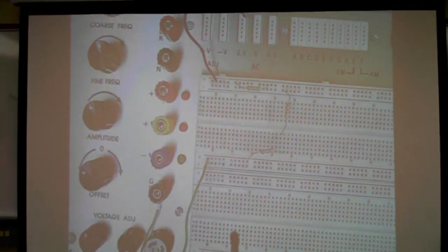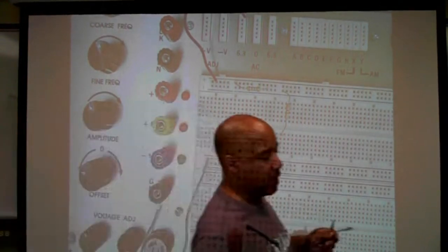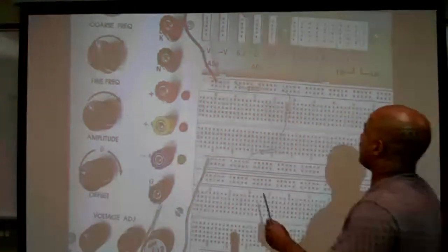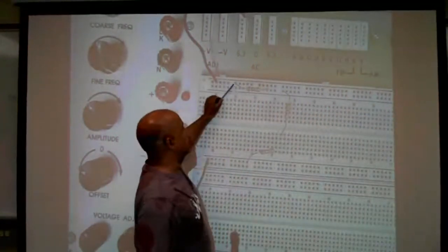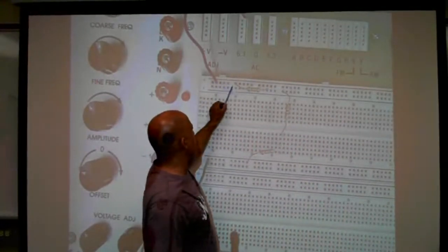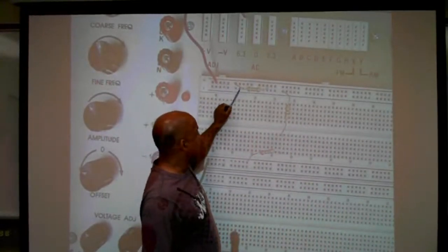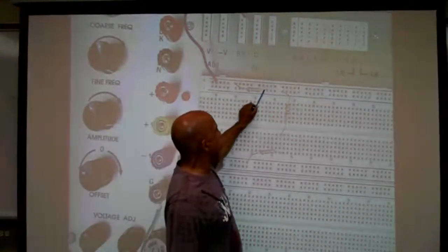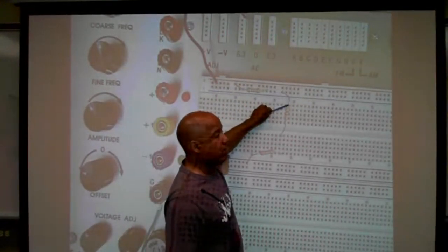And for that very first table, all you're going to do is measure the voltage drop across each resistor. Now you've got to remember where these points are. This side of that first resistor is point A. From here up to the left side of that first resistor is point A. Point B is here all the way over to that second resistor.